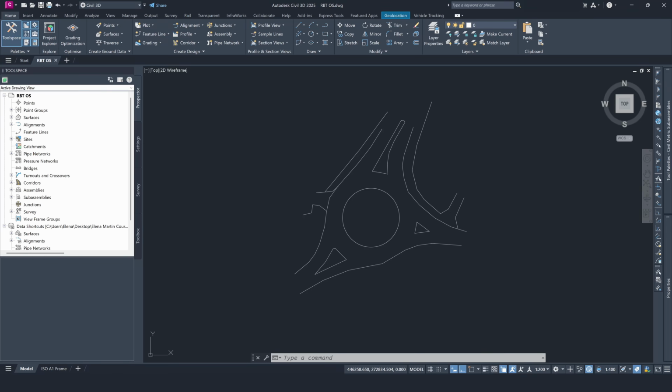At the beginning of a project, we may only have ordnance survey information and no topography to go on. This usually has no vegetation information, with only some curbing lines, building outlines, and some street names. For example, on the screen, we can see a roundabout, but the only information is that we have a couple of footways, there seems to be an access directly onto the roundabout, and it's a 3-arms roundabout.